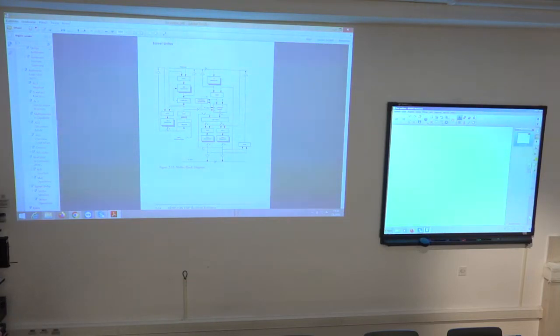So this information comes either from the instruction as immediate constant value, or it comes from this SE register that must be initialized with one instruction prior to the shift operation, and after that you simply perform shift that will use this value as information how many bit positions to the left or to the right.